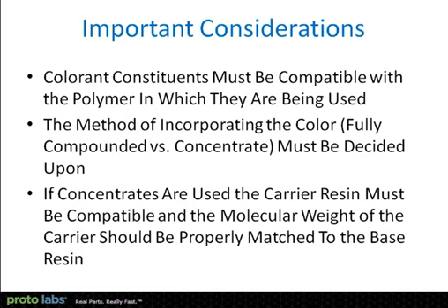And the big decision point is usually the debate between buying a fully compounded material, where an extruder or compounder has done the work of putting the color in and evenly distributing it through the matrix, as opposed to buying a color concentrate or a liquid color or a dry color, if you like, and incorporating it into the material at the point where the process of making the parts is being conducted, the so-called coloring at the press strategy.